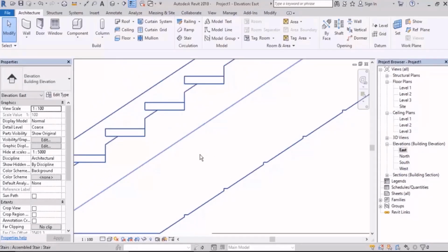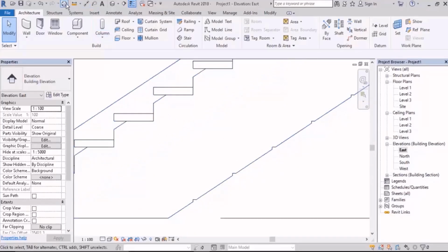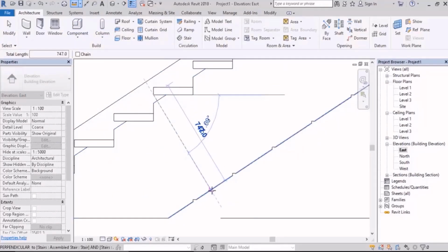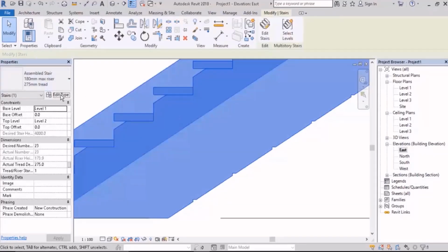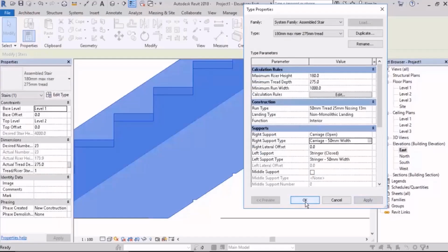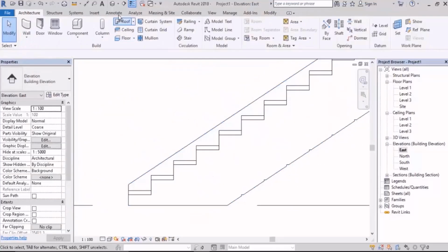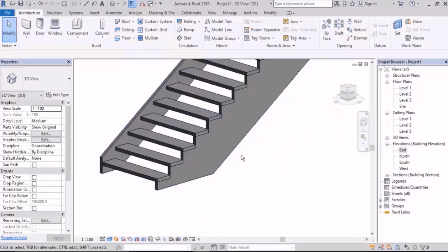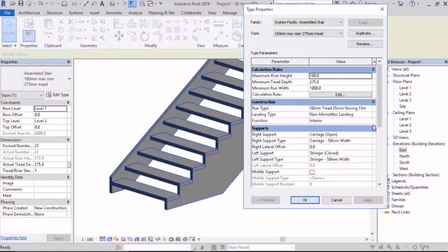Well, let's have a review together. All right, I explained too much, let's have a review. When your support is open, you can control the height of your support, all right? Or we can say that you can control your structural depth on run. For example, 80 centimeters. To not have distance in here, your total depth must be about 20-30 centimeters more than this number. For example, now if it is 85, it will be like this.